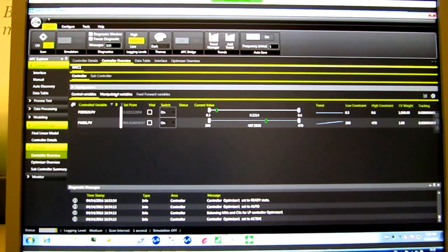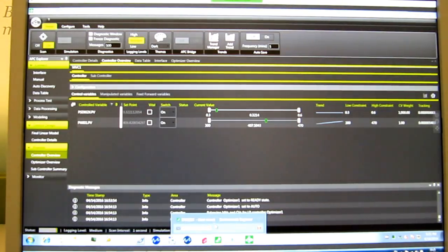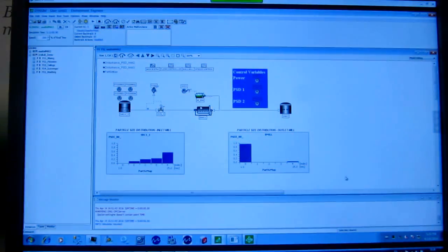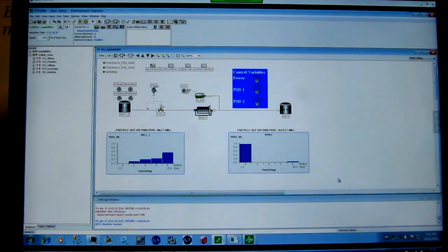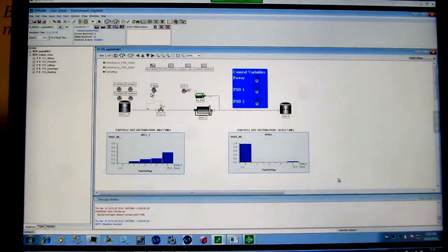Right. Okay. So I'll answer the second question first. With this example, there is no... Remember that there is no controller loop between these two variables and the power. So there is no PID loop between this and this, or this and this. In this example, it's open loop, so the operator is doing this. So in this example, we're potentially replacing the operator. I could try and find other examples where we actually remove the current PID and replace it with the APC. We can do that. If that is something that you want to use as a demo, it's something that we can look into for comparing. But for this particular example, we're not replacing a PID with the APC.